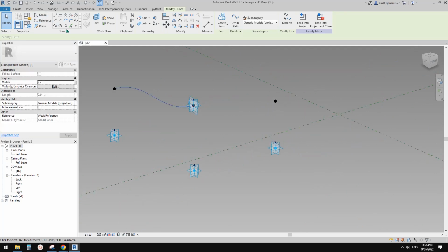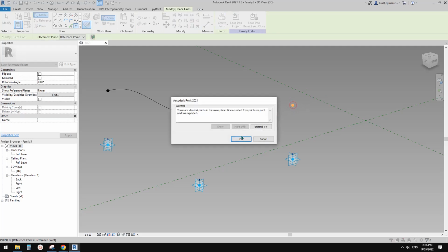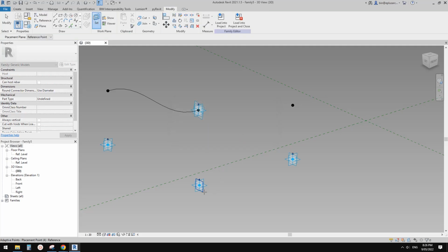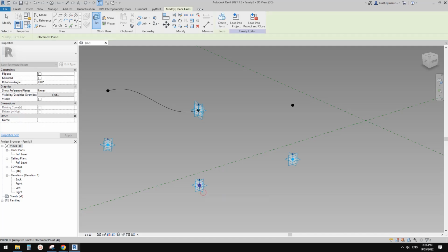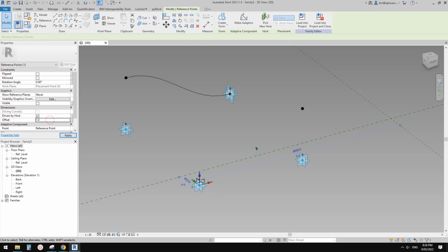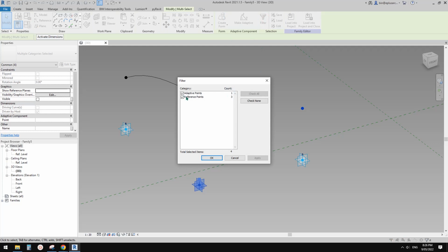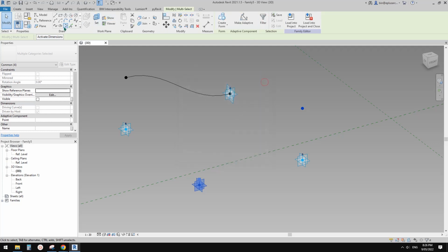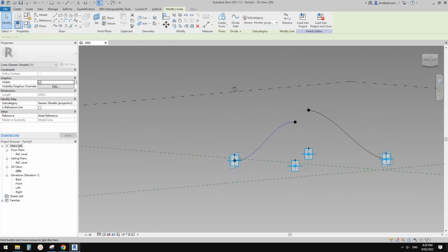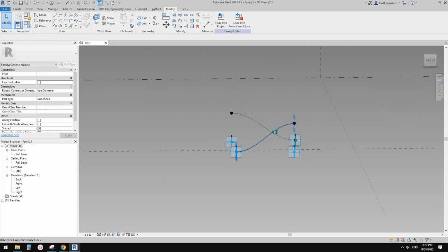First we need one from this point, and then we need another one from this point, from this vertical work plane, and place it on point 4. This one we're typing 1, and this one we're typing -1. Now we can select these 2, control select these 2, so totally 4 points, and create a spline, and this is the other one. Let's make them reference lines.